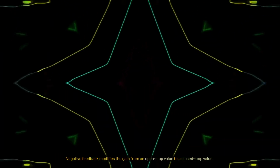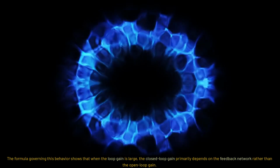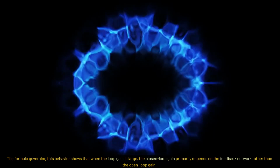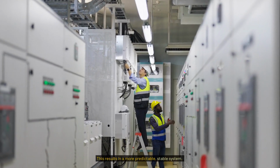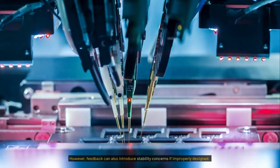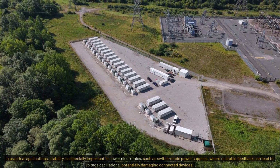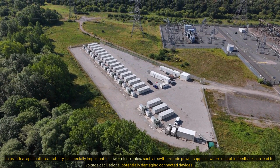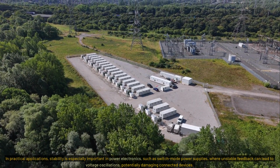Negative feedback modifies the gain from an open-loop value to a closed-loop value. The formula governing this behavior shows that when the loop gain is large, the closed-loop gain primarily depends on the feedback network rather than the open-loop gain. This results in a more predictable, stable system. However, feedback can also introduce stability concerns if improperly designed. The chapter covers stability analysis and corrective measures. In practical applications, stability is especially important in power electronics, such as switch-mode power supplies, where unstable feedback can lead to voltage oscillations, potentially damaging connected devices. Engineers designing power systems must ensure that feedback circuits are stable to prevent erratic behavior.